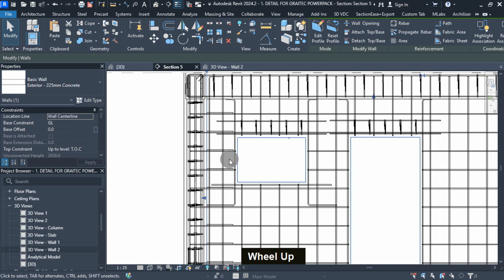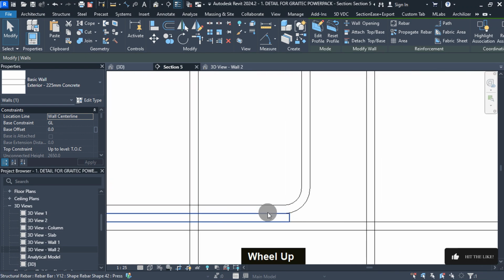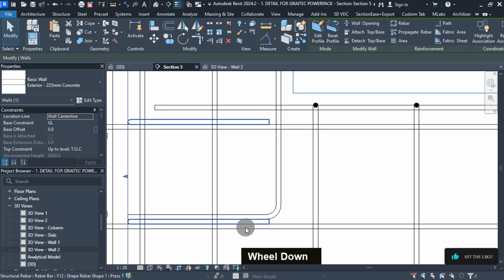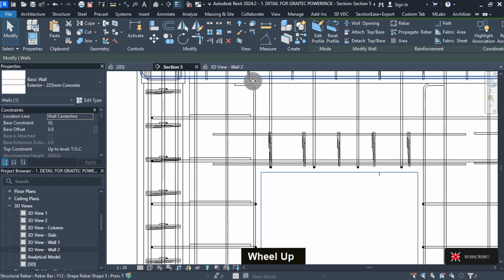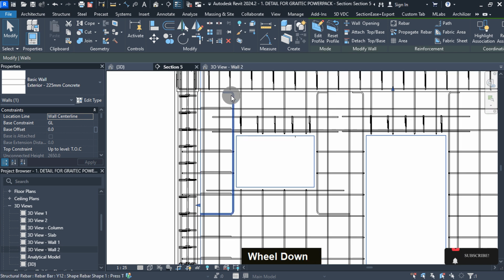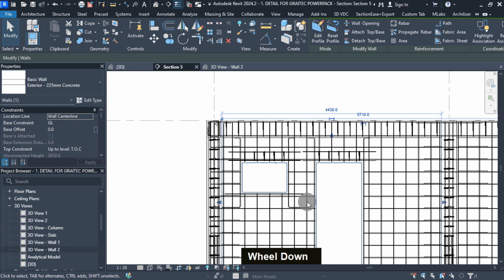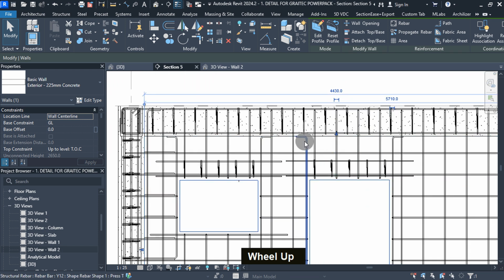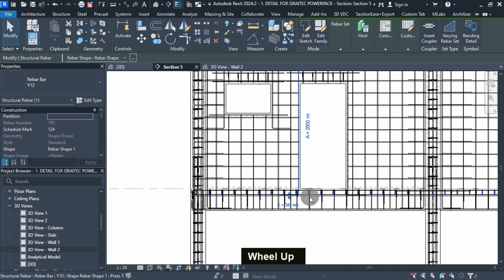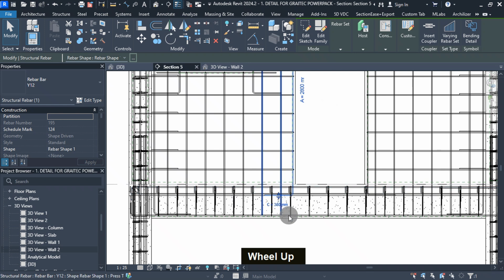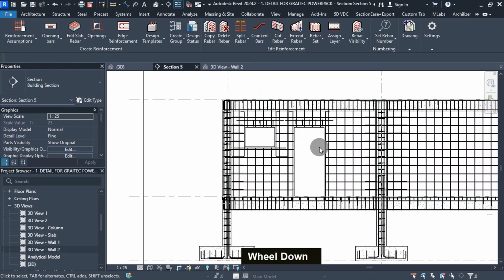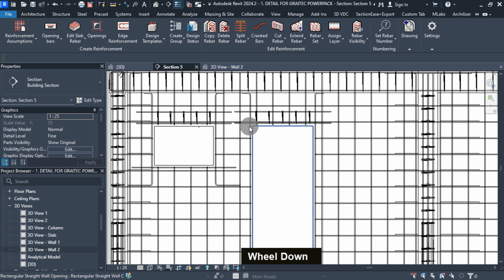The vertical constructive bars have been updated at the opening as discussed, and the bottom bend now rests on the U-shaped edge bars as required. The top offset has also been updated, as you can see, and the bars have been tied below the top beam. These bars can be modified separately using the opening bars command provided by the plugin. Remember to use the required specification design when modifying the bars with the provided tools.